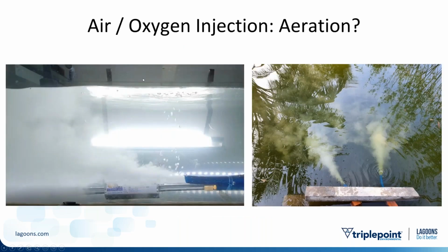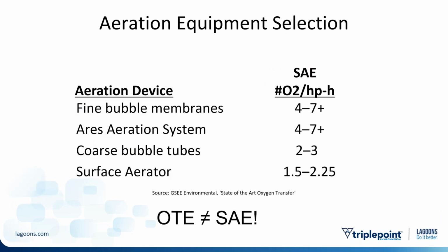And lastly, there's this new concept of air injection or oxygen injection into micro bubbles. I put this as a question mark. Is this actually aeration? This is oxygenation, but because the bubbles are so small, they kind of float in the water column. They don't really rise rapidly. They don't create a mixing action. Are they really completing the EPA definition of aeration? I say I don't believe so. This is more of a supplemental oxygen addition, but this is not something we see used very commonly because of the lack of mixing.